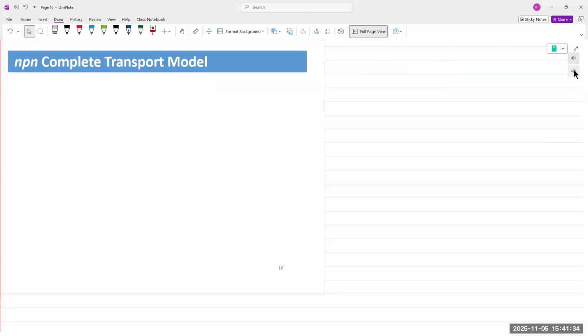So IC can be written as IS times e raised to VBE over VT minus 1. And then, oh, sorry, we actually combine both of them together. So it'd be e raised to VBC over VT, subtracted because it's flowing in the opposite direction.